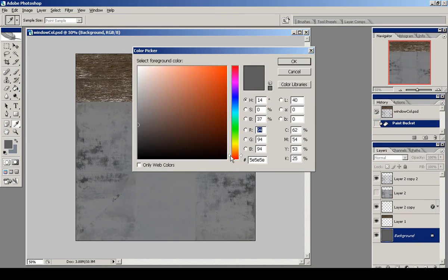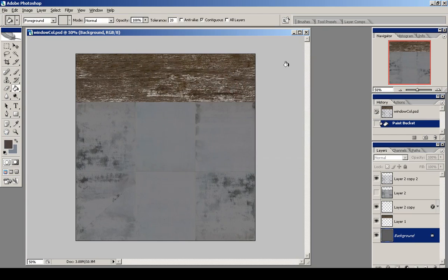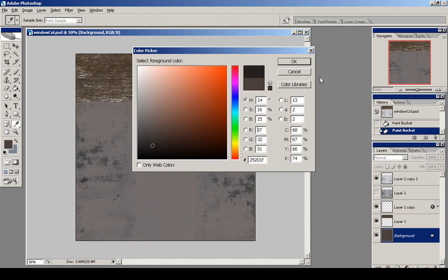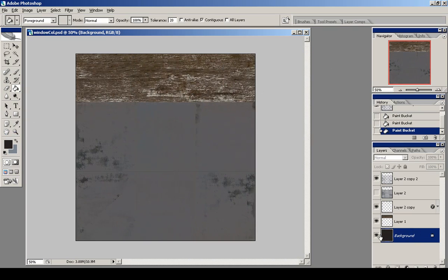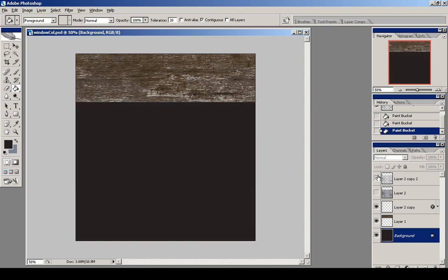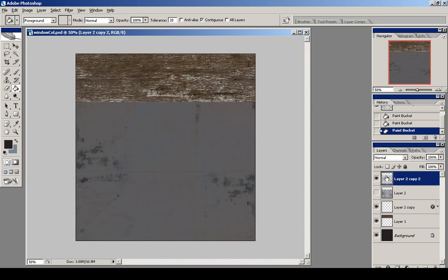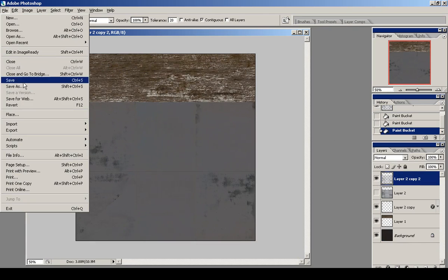Now if you see, I took a sample of the coloring from the alpha map and I put down that color in the background of the color map. That's so if we were to have a white color in the background of the windows in the color map, there would be a white outline around all the stains, which would appear very ugly. So if you have a gray color or a color closer to the stains on the window, then the outline is going to be that color and it's going to blend in a lot better.